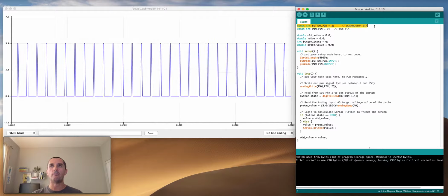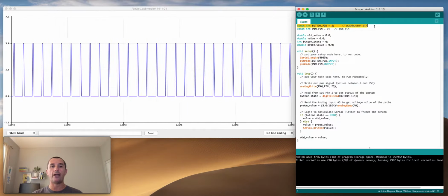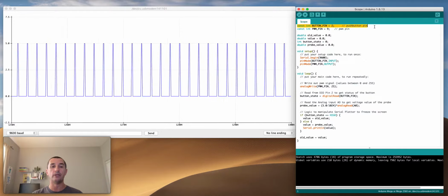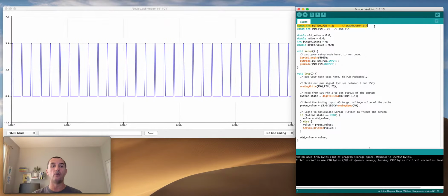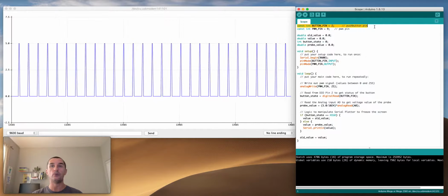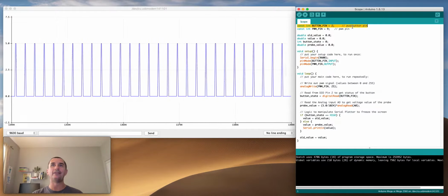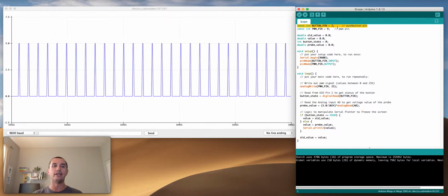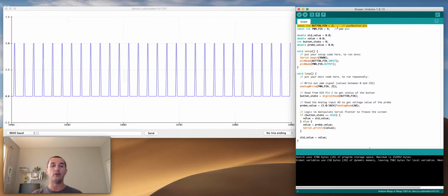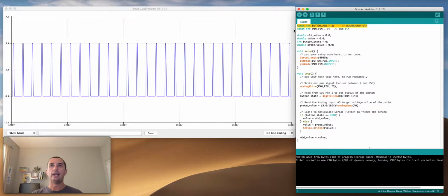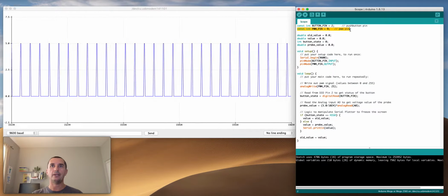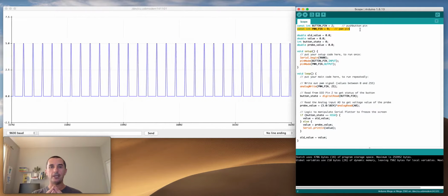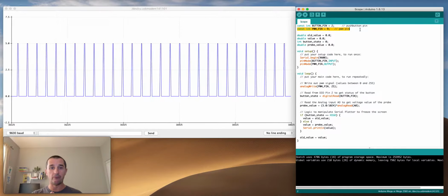And if you remember from the previous video, when we wired our button into the digital I/O port of the Arduino, we wired it to digital I/O 2 or pin 2. And so we've defined this here now, is that we're going to be looking for the button state on digital I/O pin 2.